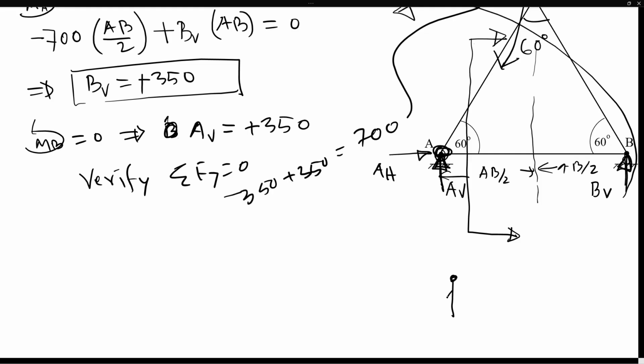So you got a vertical reaction at 350 pounds, and then AB is acting in this direction and AC in this direction. Remember, we're not seeing the point B or C. We are ignoring everything to the right side. This C is C and BC is just for our notation of this force that we are calling AC, and this force we are calling AB.